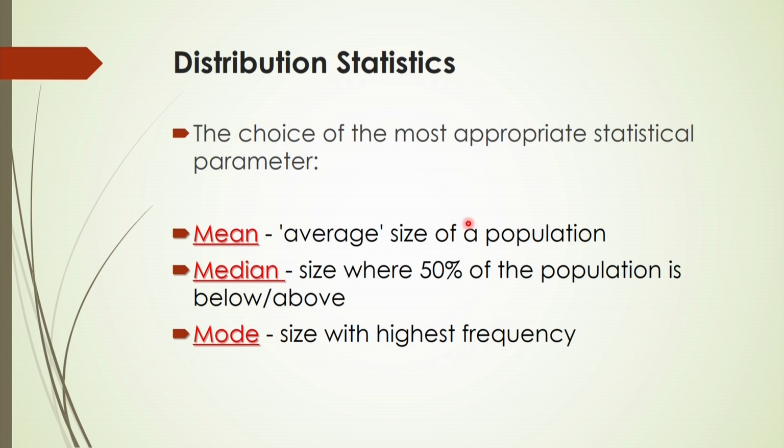Of course, if you are having the highest frequency, that means that particles will be more in number in the sample. And also mean, sometimes from lower range to higher range, there are different types of means. You will get sometimes arithmetic, sometimes surface mean, sometimes volume mean, volume surface mean. Definition will be shown later on, but you have to know what should be the mean size of the particles, by which you can analyze the further efficiency or simulation purpose or modeling purpose. You have to know the particular size of the particles. So, you have to use the mean size of those particles.